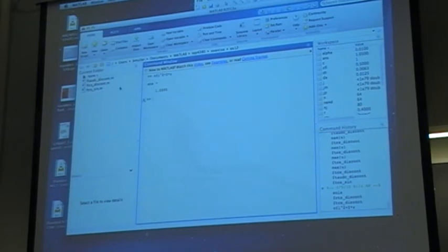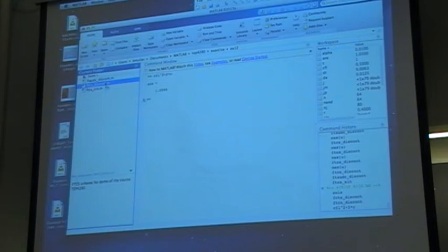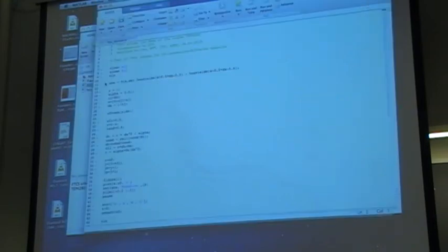But I want to show you another thing, and that is when we violate the condition on the Peclet number. So we violate it now in the way that we reduce the number of grid points and thereby increase, in that case, the delta x. So then we will violate this condition here.